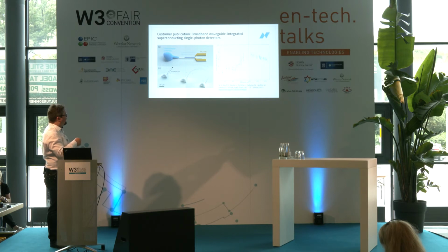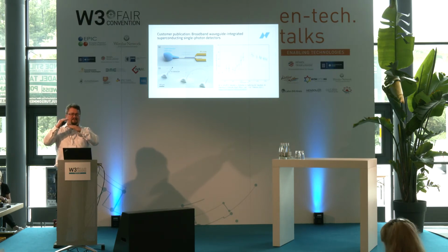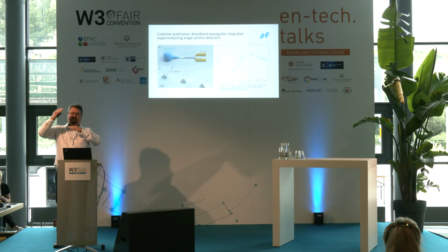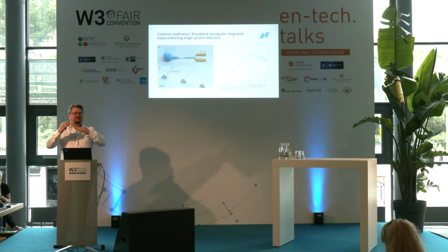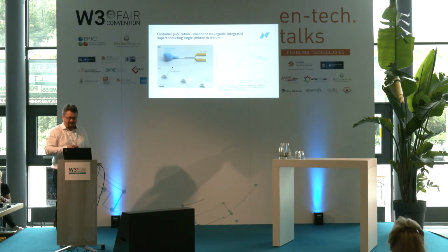But now, instead of having a long curving waveguide, they have just added a mirror here. So light goes in, is reflected at the mirror because the interface between the polymer and the vacuum or gas has a total internal reflection, and then the light goes here into this waveguide. And in this waveguide, it is picked up by this superconducting nanowire. And superconducting nanowires are an established technology to detect single photons because they can be driven very sensitively close to their superconductive normal state. And thus you can take a single photon, the energy from a single photon, and generate a macroscopic resistance signal from that.